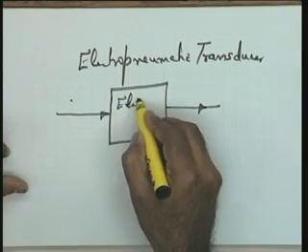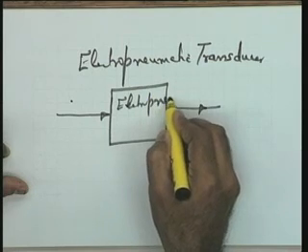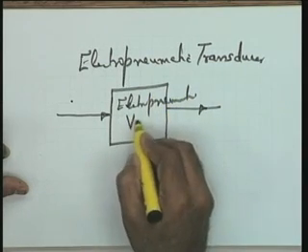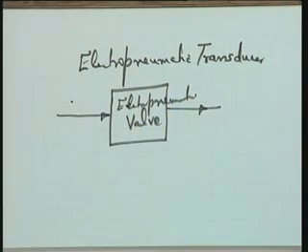Electro-pneumatic valve, sometimes referred to as electro-pneumatic valve. You see that this is again a must, because if you want to cash in on the power of digital computers or op-amp circuits for realizing your control functions, you really require a compatible device between the control valve, which we have discussed, and that controller.